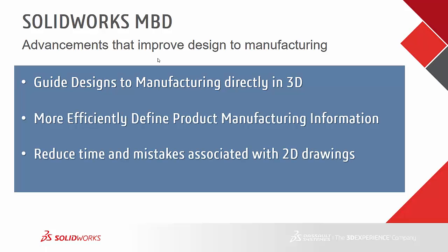As we hope you see from the webinar, using SOLIDWORKS MBD and DimXpert is really going to guide this design to manufacturing process directly inside of 3D. This is going to be a much more efficient process as opposed to creating 3D designs and then translating everything into a 2D design or a flat paper drawing. With this, we're going to be able to reduce a lot of the time and mistakes associated with creating those 2D drawings by keeping everything natively in 3D.